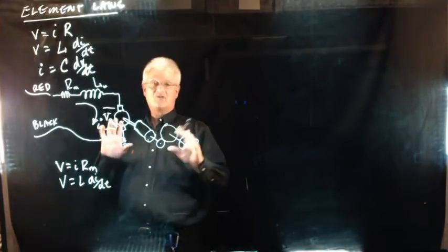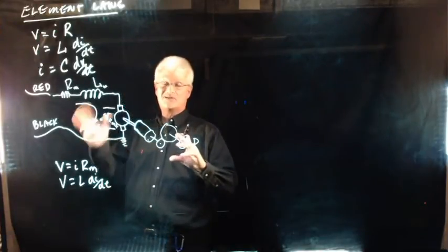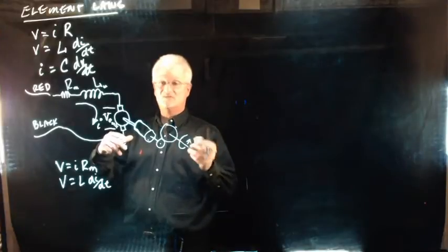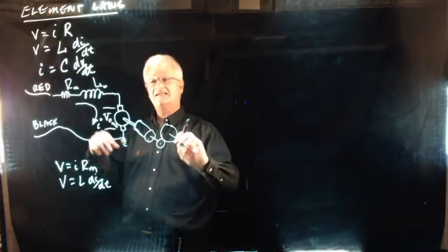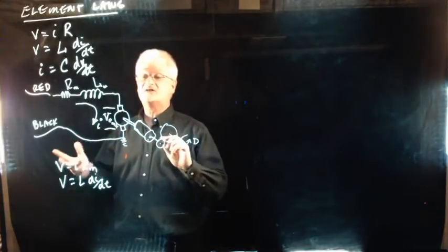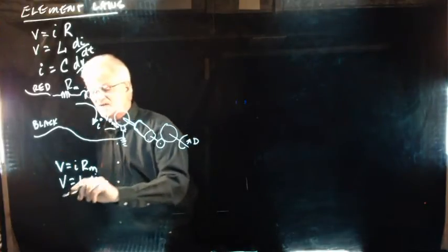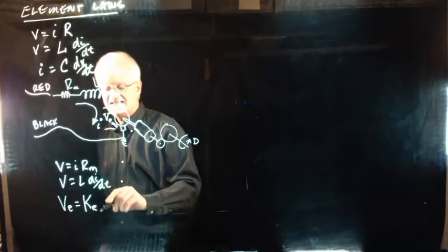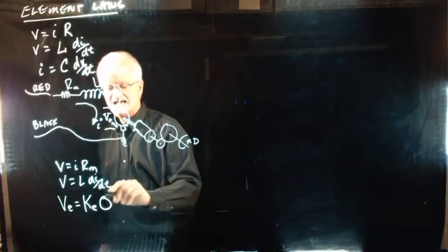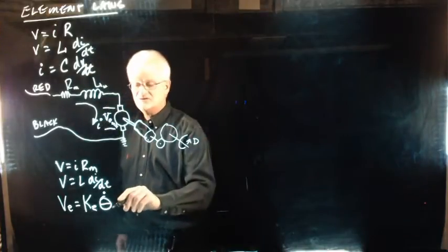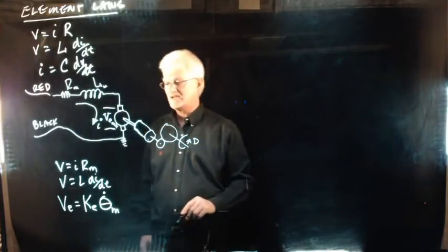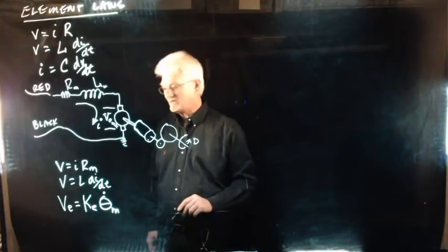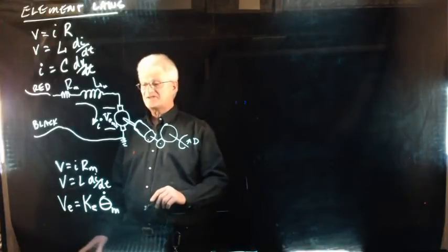Motors work in two ways. If you put a current into the motor, it makes the motor move. And if you move the motor by hand, it generates a current. That current is the back EMF. There's a motor constant called the motor EMF constant, and the voltage across the motor is proportional to the velocity of the motor. So we're going to write it that way. And now we've got all the electrical parts of the equation.